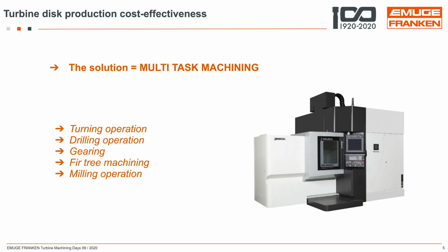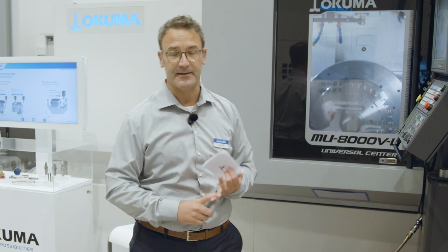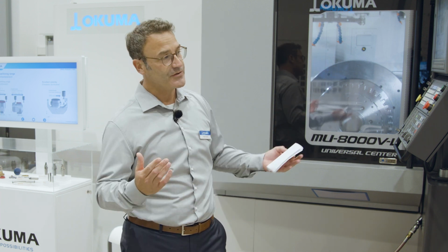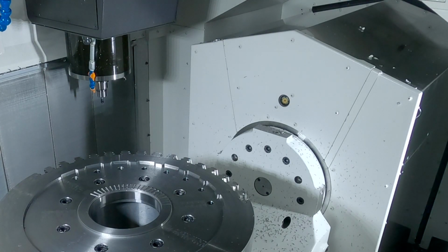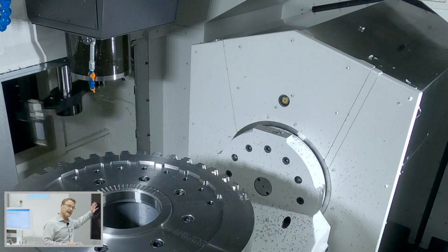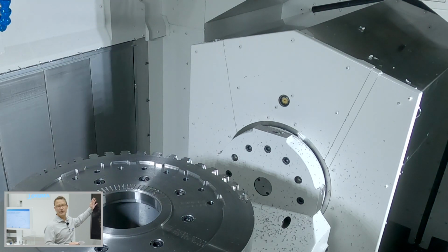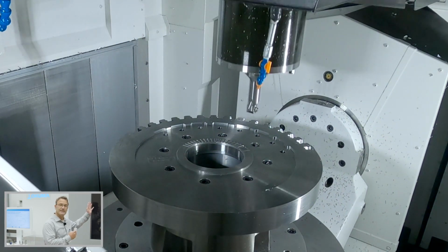Over here the C-axis itself, the table, is up to 800 RPM. We have more than 1000 Newton meter torque, so we can really have a highly efficient machining of titanium and rough material, which is outstanding in the market. In combination with the 20,000 RPM spindle, which we have at the moment with 85 Newton meter torque, a huge variety is possible. But that's not the only spindle.